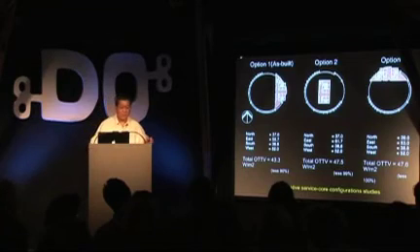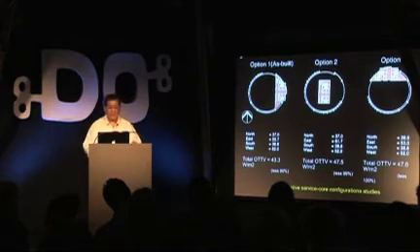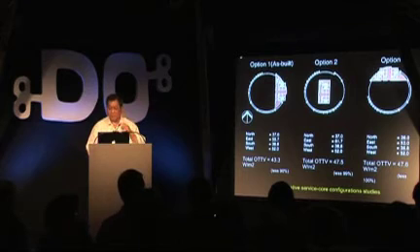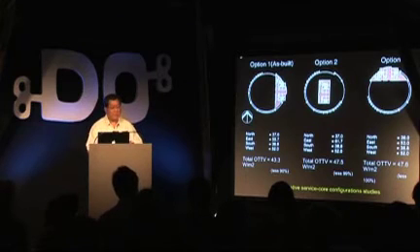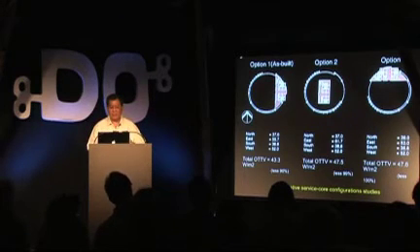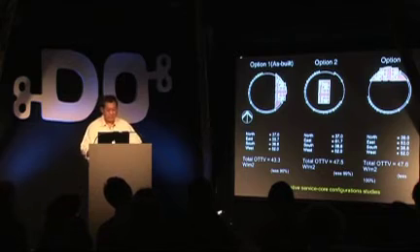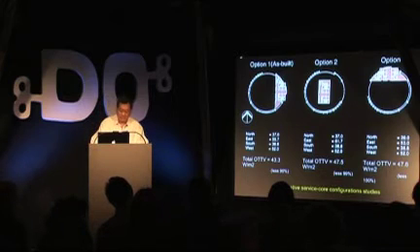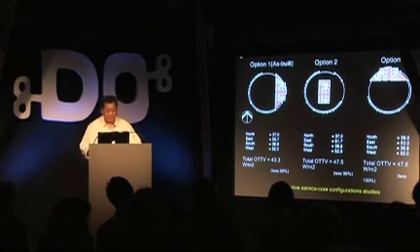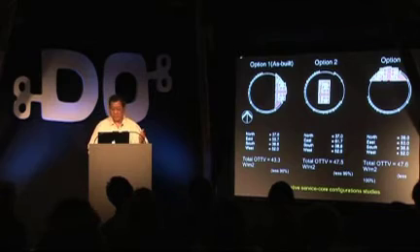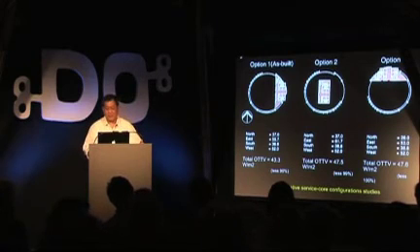Now, the diagram on the left shows the tower as it's built. You can see the core on the east side, and then we look at option 2, which is core in the middle, or option 3, which is the core to the north. This is to illustrate that shaping of the building is extremely important at the outset. We took an index which is called OTTV, which stands for Overall Thermal Transmission Value, and for the first one is 43.3 watts per square meter, second is 47.5, and the third is 47.6.